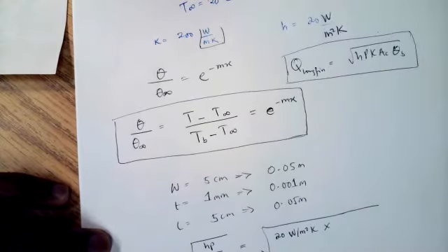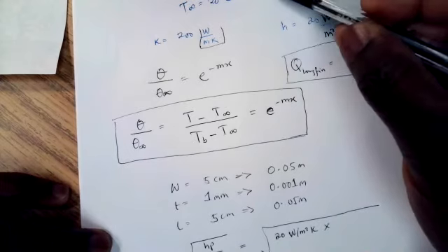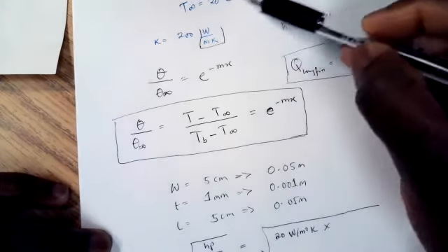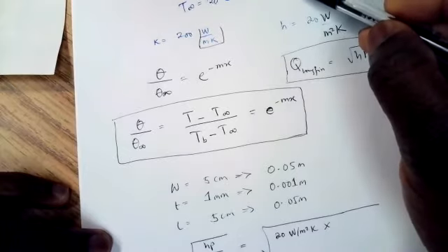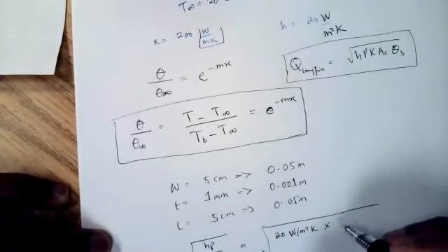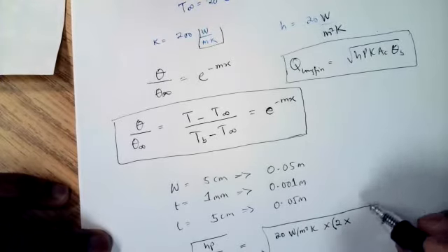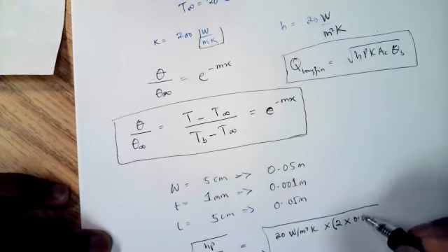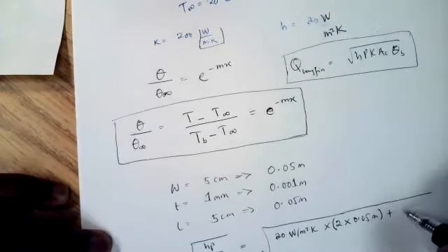Now, the perimeter of the fin, okay, we'll just multiply the width by 2 and then add it to the thickness multiplied by 2 just to get the distance around the fin. Okay, so this is 2 multiplied by, putting all this in one bracket, 0.05 meters plus 2 multiplied by 0.001 meters.